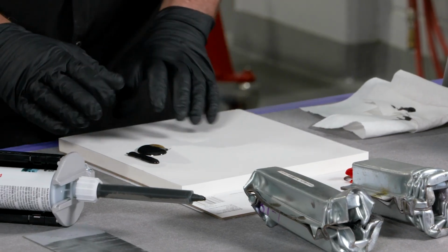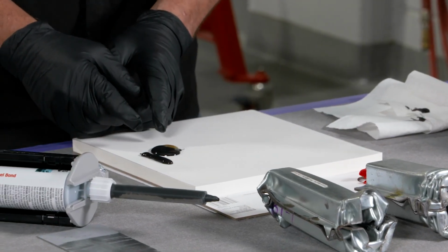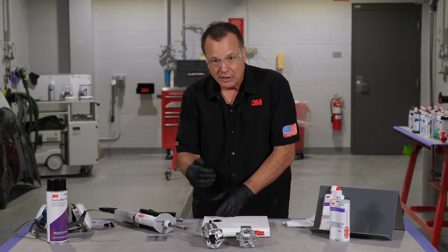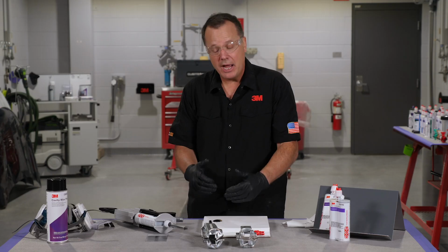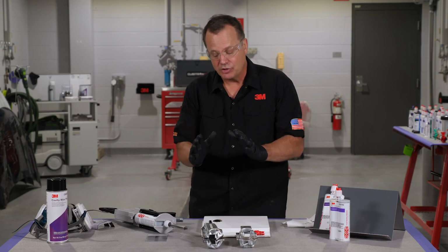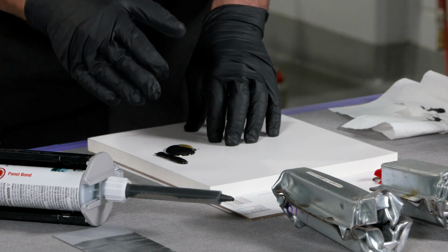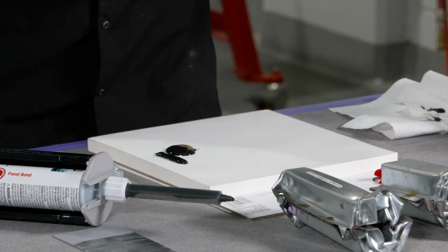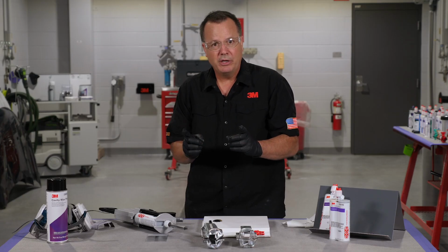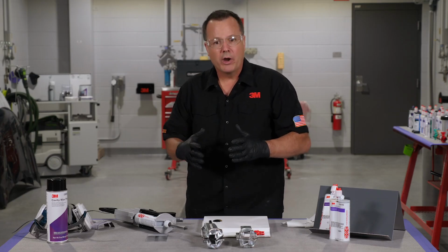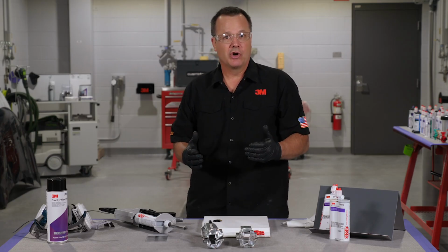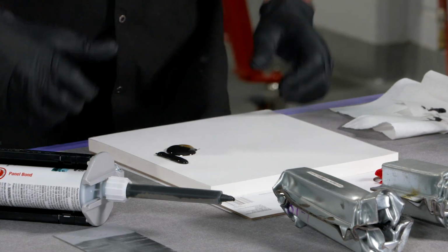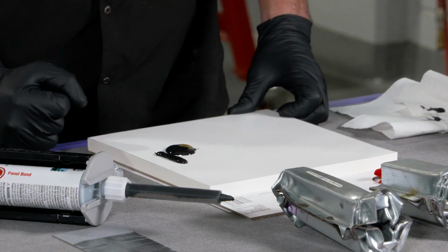So you may have noticed as I extruded the product from the cartridge that one side came out before the other. So had we not equalized that or balanced those cartridges, we may have had an uneven mix that may not have cured. And there's enough adhesive in that nozzle to put out a bead quite long where that whole area may not properly cure. So again, emphasize that importance about equalizing that cartridge to get a proper mix.